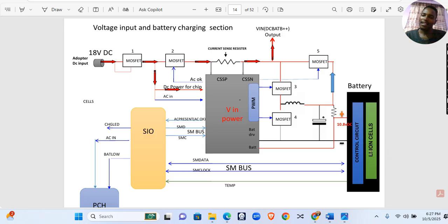Yes. And this one represents the lithium ions, which means these battery cells are made up of lithium ions. These cells might be faulty, right? Yes, because each battery cell must contain an equal amount of voltage. If you have 4 cells, each cell should contain the equal amount of voltage. If it is 3 volts, each should have 3 volts. In case one of them has less than 3, maybe 1.2 or 1 or 0, it means one of the cells is faulty and you need to replace your battery, right?